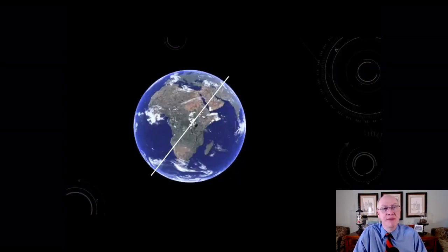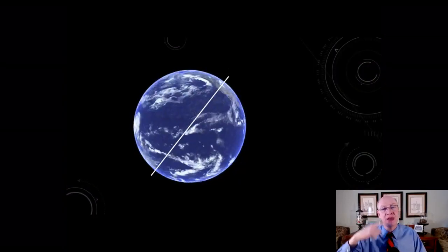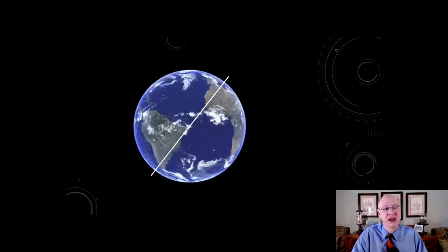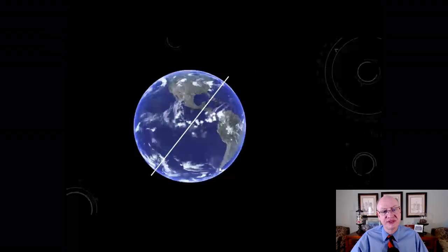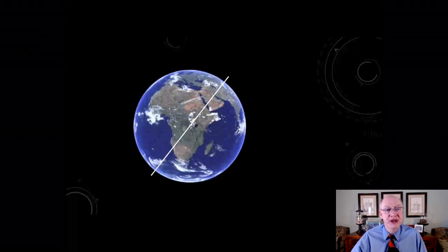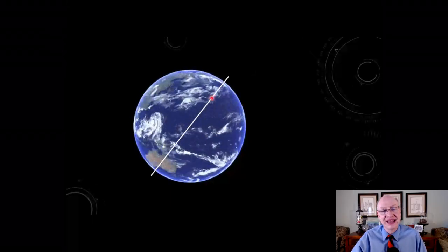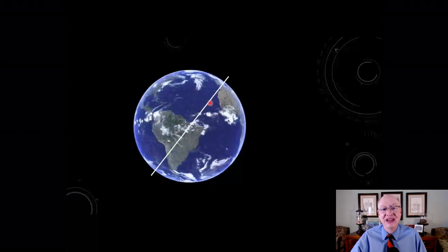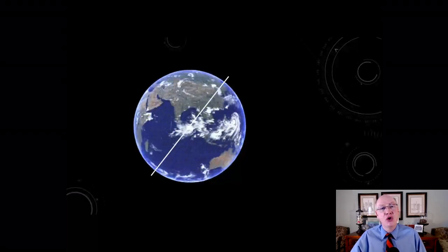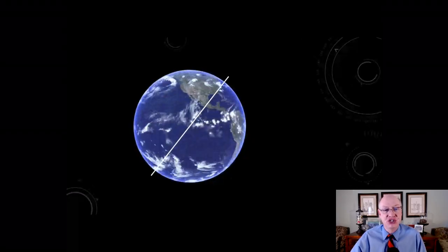Now, an important thing to remember always is that as your spacecraft is orbiting, the Earth is rotating underneath your orbit. So if there is a particular orbit that you want your spacecraft to get into, there are 2 periods a day where your launch site is underneath that orbital plane. And if you launch at that moment of time, you won't have to do an orbit plane change maneuver.